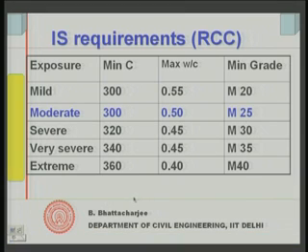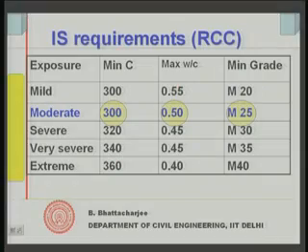And if I use this, then my cement content should be this, my water cement ratio should be this, and my grade of concrete is M25. Anyway, we have chosen grade of concrete M25 right in the beginning, because we said it is moderate exposure. Had it been any other exposure, one had to choose the grade of concrete accordingly.